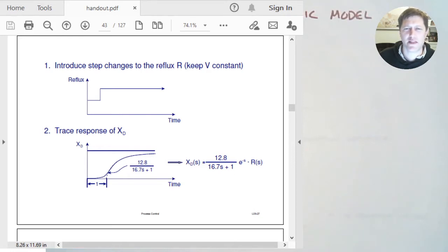Okay, so you've plotted some data here as XD changes with time, and we've seen from the previous mini lecture that we would expect this to be slow to begin with, some delays, and then it would tend to then approximate a first order response after a little while. And we saw that we can simplify this by extrapolating down at this point of inflection here, extrapolate back at constant gradient to the XD equals 0 line, and then we can treat this first period as simply a delay in the response, and the second period we can treat simply as a first order response.